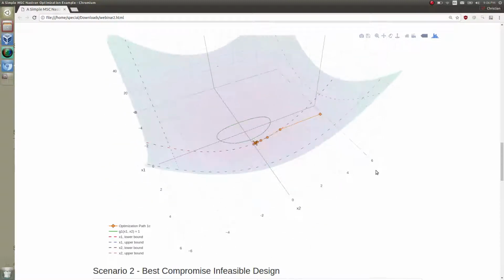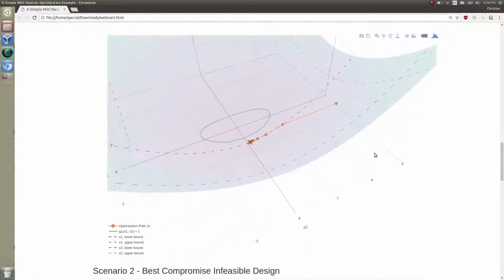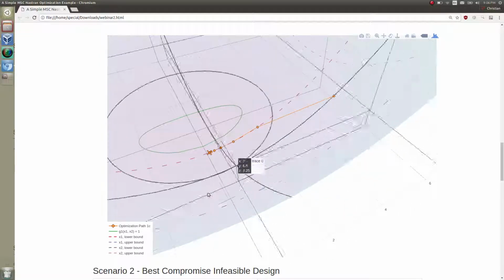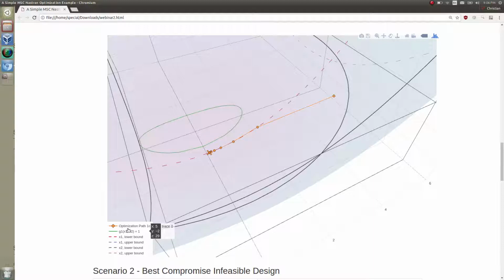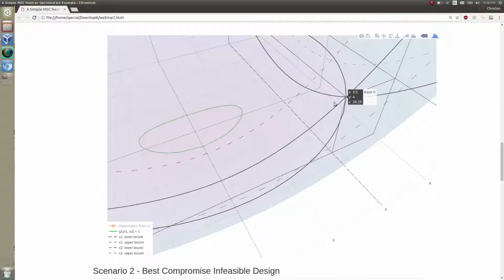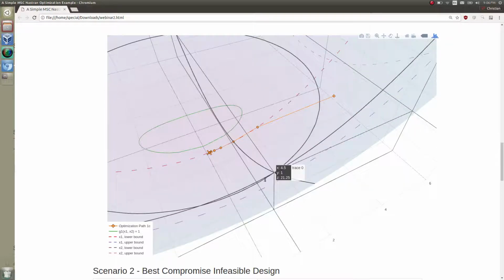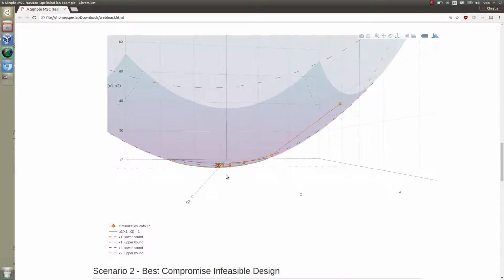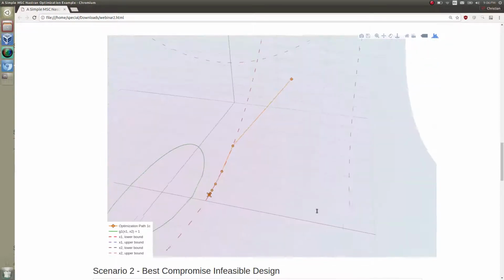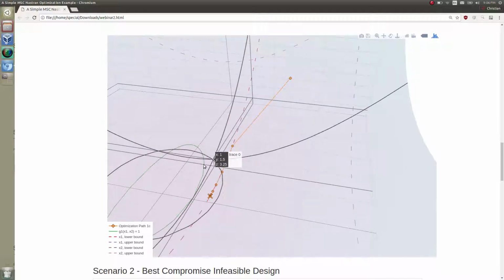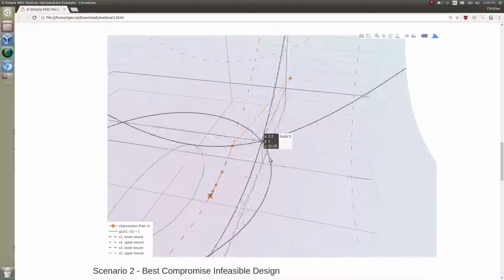Let's look at what the optimizer does before we go ahead and go through the process of doing this in Nastran. Like before, Nastran will start at the initial point here, 3, 4. It will make a move towards the local minimum that you see here, but then it touches the side constraint first before hitting the design constraint we previously defined.